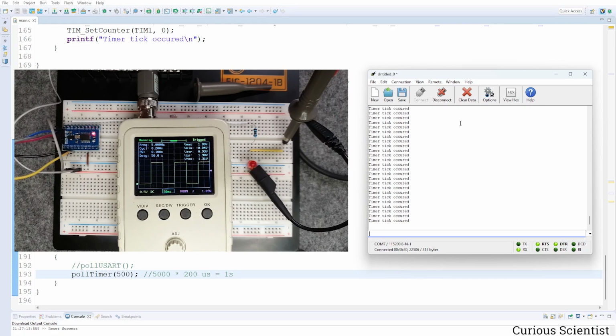And then this way, actually, you can define the tasks so they don't have to wait until the delay time has passed, but instead they just poll the timer, and when the timer has counted up to enough time, then the tasks can run. So for example, now I'm blinking an LED quite often, but I don't have any delay in between 2 blinks.